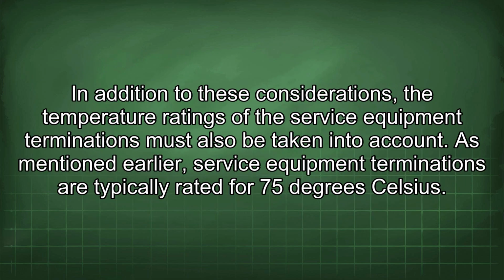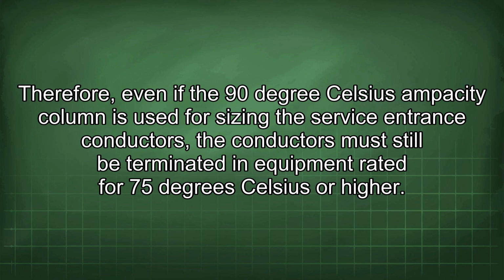In addition to these considerations, the temperature ratings of the service equipment terminations must also be taken into account. As mentioned earlier, service equipment terminations are typically rated for 75°C. Therefore, even if the 90°C ampacity column is used for sizing the service entrance conductors, the conductors must still be terminated in equipment rated for 75 degrees Celsius or higher.